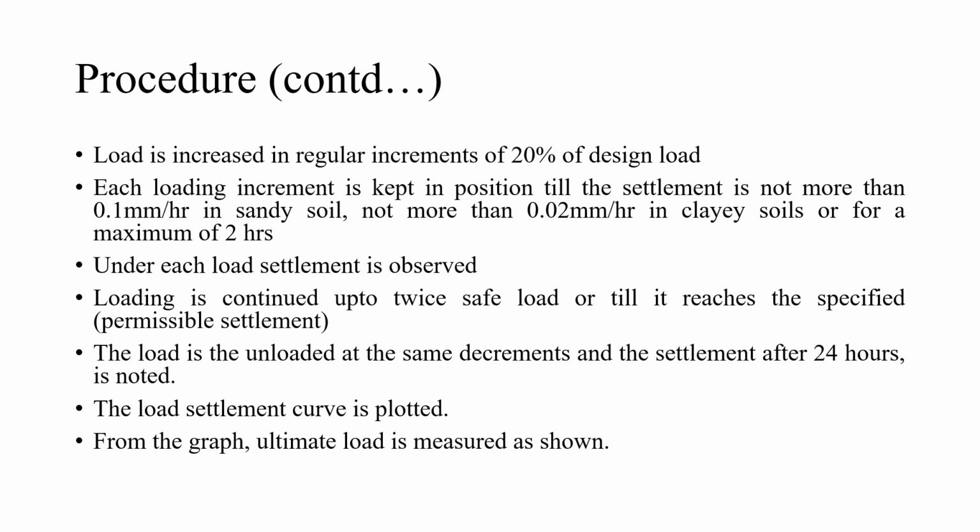You keep on increasing till it reaches the design load, and under each load, the settlement is continuously being observed. The loading is kept on continuing till twice the safe load that we have calculated from the static analysis, or till the settlement reaches the specified or permissible settlement that is obtained from the code for any particular building.